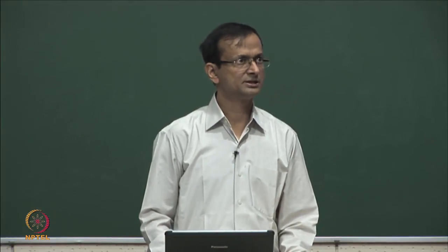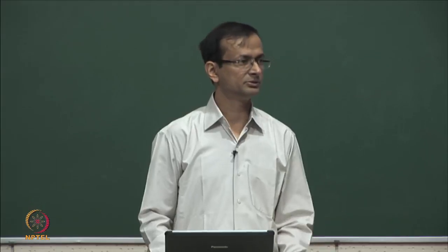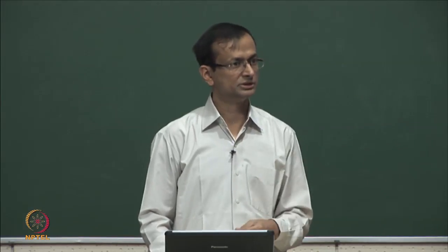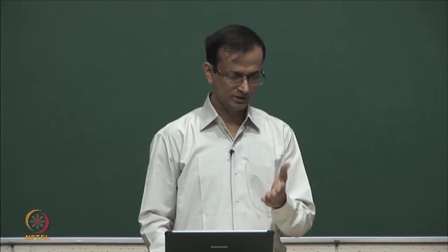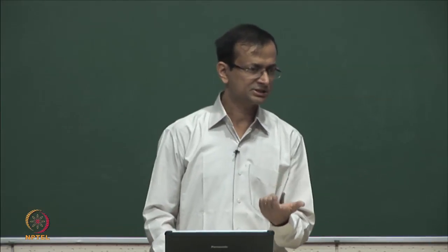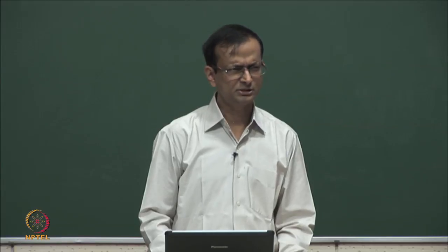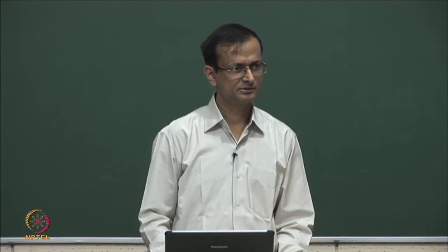Simulation, a gate level simulation, does tell us what the delay is. If you set the input, the changes at the inputs of the gates will propagate to changes in the outputs, and when you see that the output has stabilized, that is how much time the logic has taken. So, could I use this as an alternative or not? Simulation requires what other input than the netlist itself?